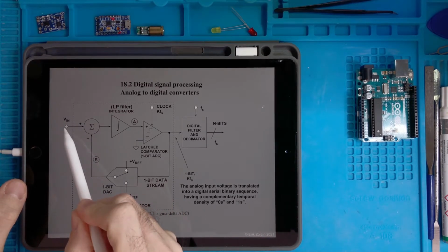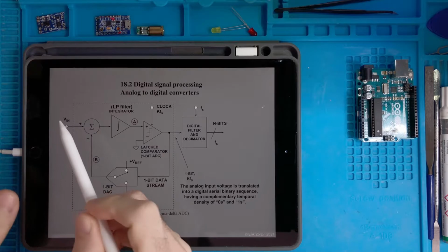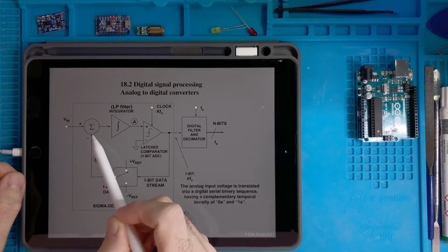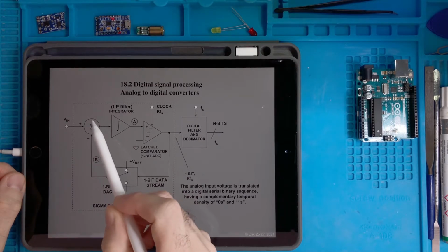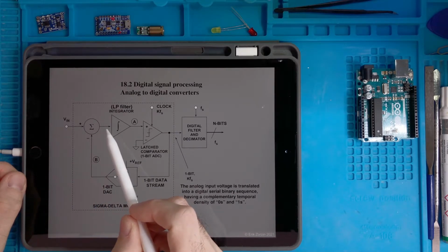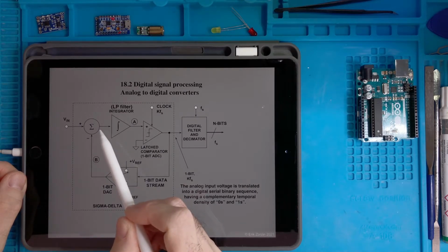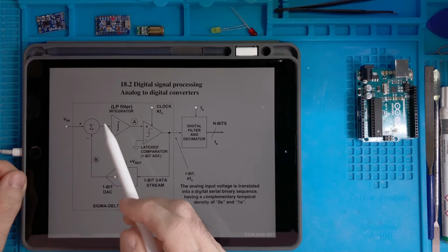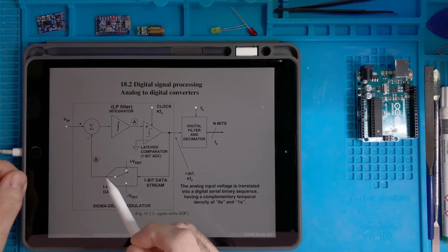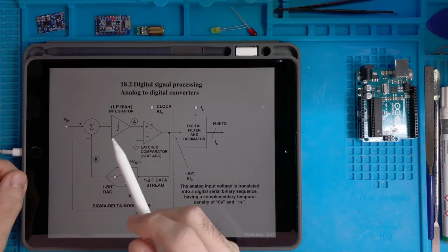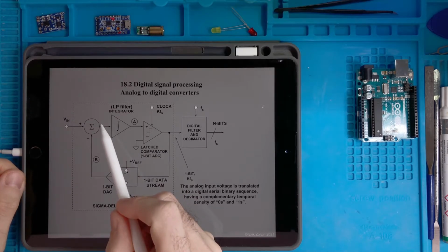We have an input, so our variable, a voltage. It enters a differential amplifier implementing a summating node. This thing has two inputs, the plus and the minus. So the output of this thing would be a coefficient alpha multiplied by V in plus beta multiplied by this input, which is the output of this thing here. So here we will have a certain value.